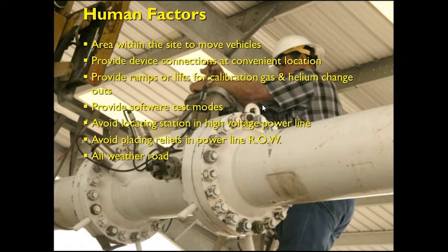But they also layer in some gas detection and automatic shutoffs on equipment and alarming capabilities. Other companies have the philosophy that they're going to put the gases and the analyzer section in a second room of the building, and they'll make that a Class 1 Division 2 build-out and put the controller on a general purpose side of the building.